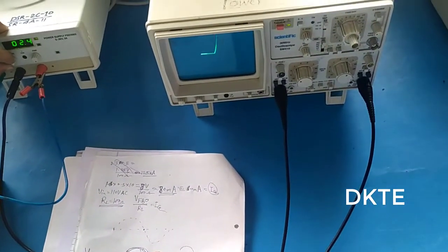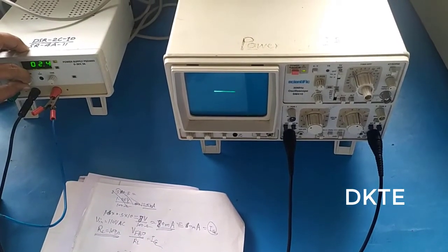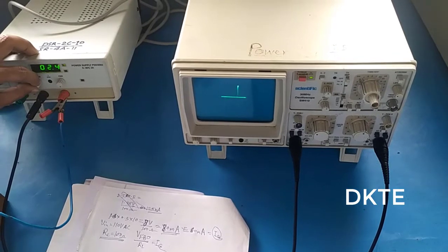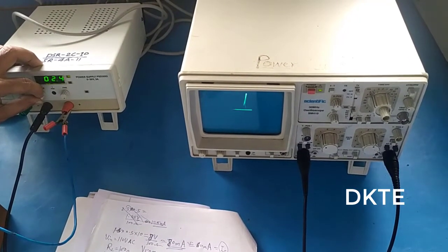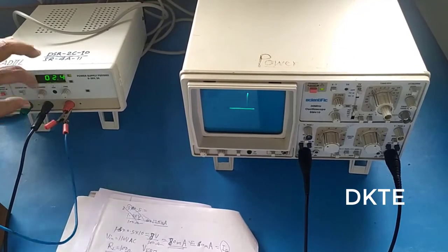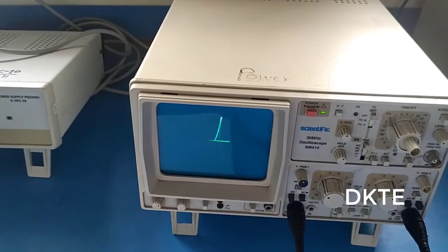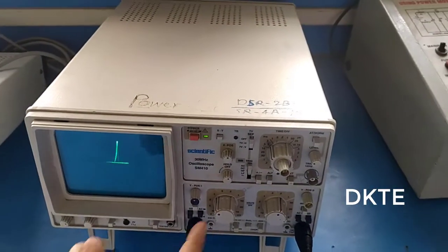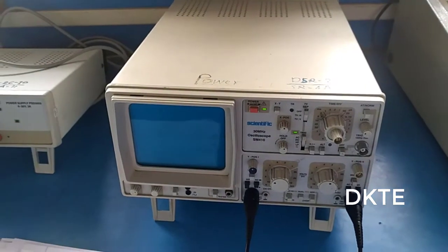that Ig you can vary, and with that Ig you can vary the forward breakover voltage also. See, you can vary this Ig, vary the forward breakover voltage, and then the corresponding IH. Then you can observe the SCR voltage and current waves.